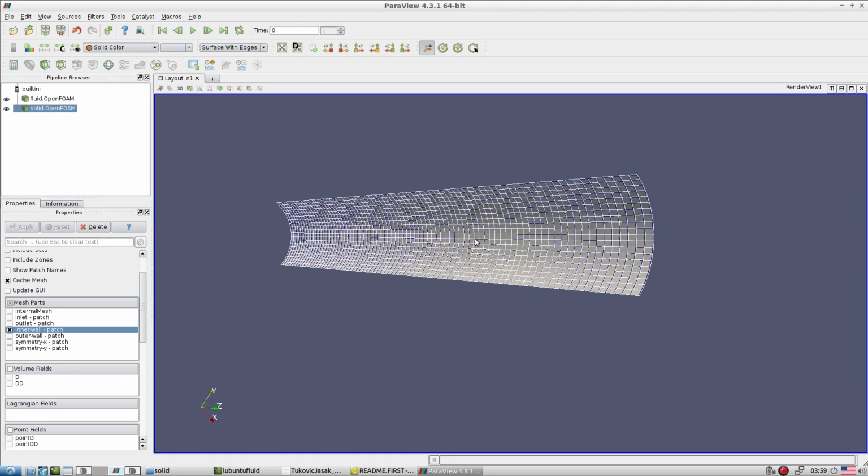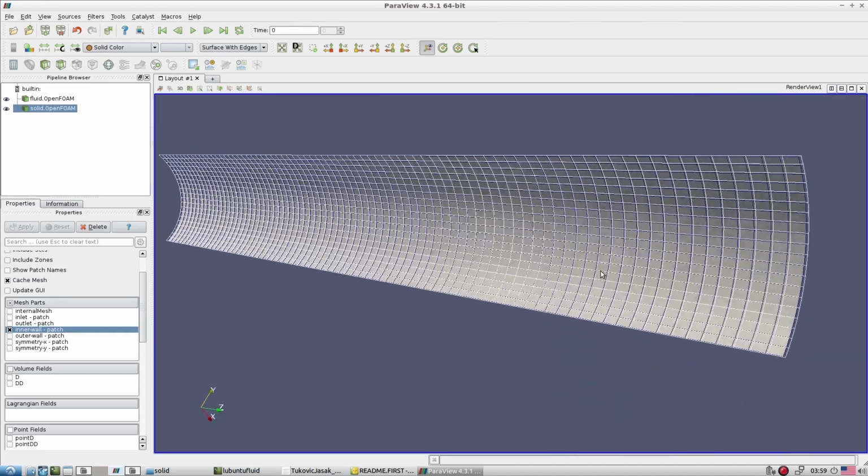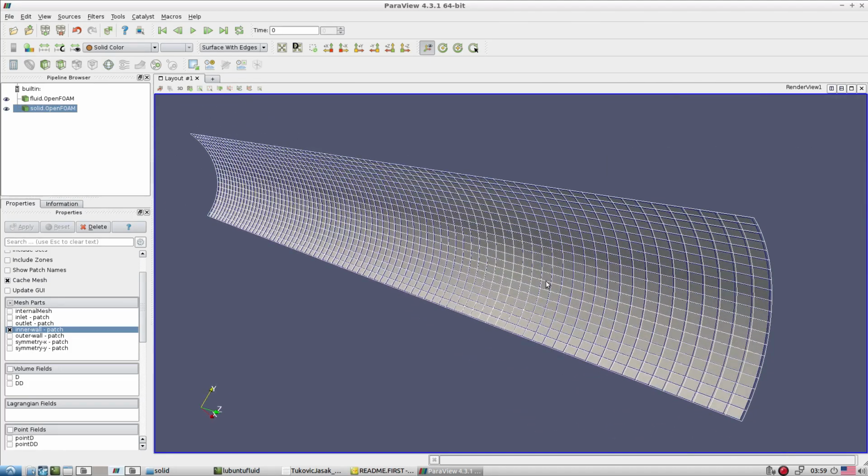Within that structure we solve the deformation equations, and after that we see the motion for this particular patch. We are not going to move the solid patch in this solver, it remains there, but accordingly we move the fluid patch. That is the idea behind that.